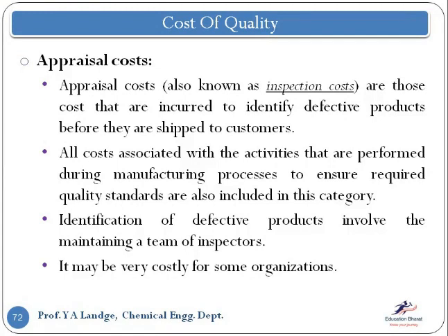Now this is very important, because as we are working on quality, ultimately we need to set up a lab. We need instruments, because when you are checking the quality of the lubricating oil, we need a lab with instruments for checking the density, the viscosity, the flash point, the fire point, all this. Why? Because we want certain machines, the instruments, so that we can check it. We want the GC, all this. These are the instruments that are used for knowing the component properties.